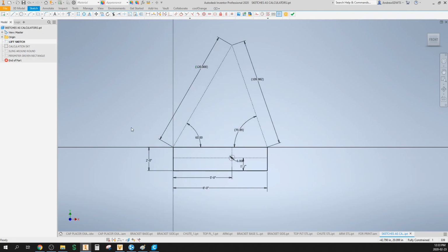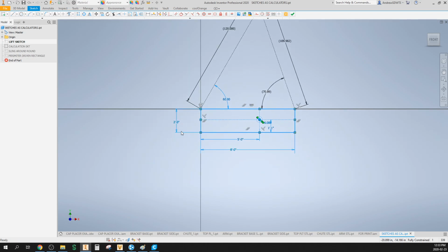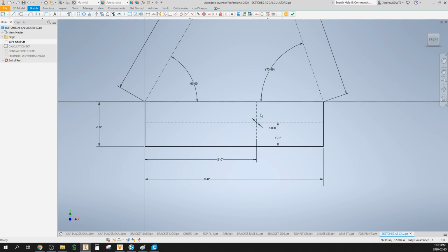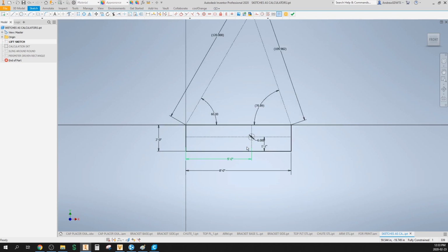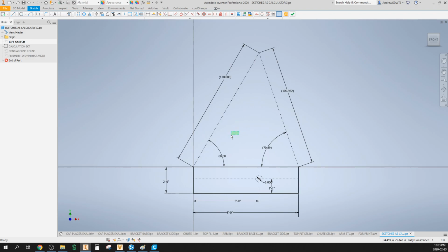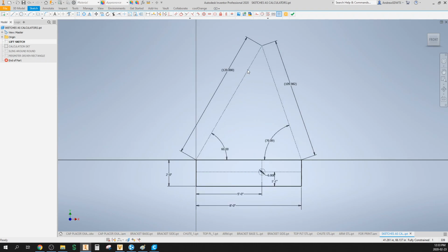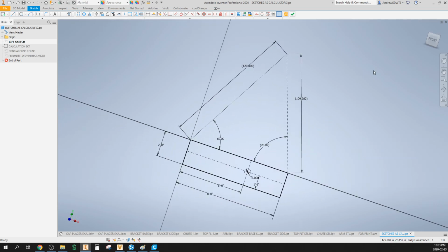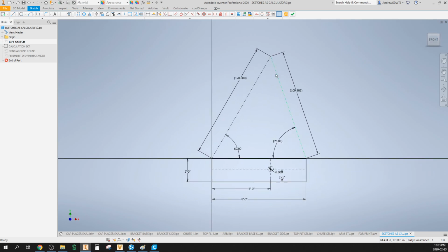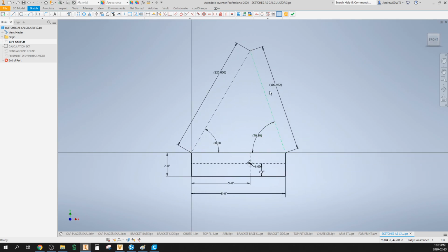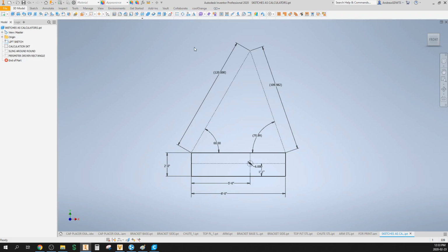This is just a simplified lifting diagram for this rectangle. This rectangle is 8 by 2 feet, and the center of gravity is offset. It's off the center by a foot. I want my two slings up here to have a minimum sling angle of 60 degrees, so I've set that. And I want my hook to be above my center of gravity so that this thing doesn't want to list one way or the other. So I've constrained it like that, and I get a resultant sling angle and sling length. That's handy. It figures that out for me.